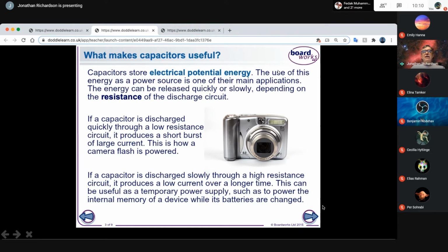That decoder requires power. So the rails provide power to the decoder. And what happens if, for example, the train passes over a dirty piece of track? It loses contact with the wheels. The wheels transfer the power into the decoder, but every time it passes over a dirty piece of track or corrosion or whatever it may be, I would lose power. Therefore, I would lose the control.